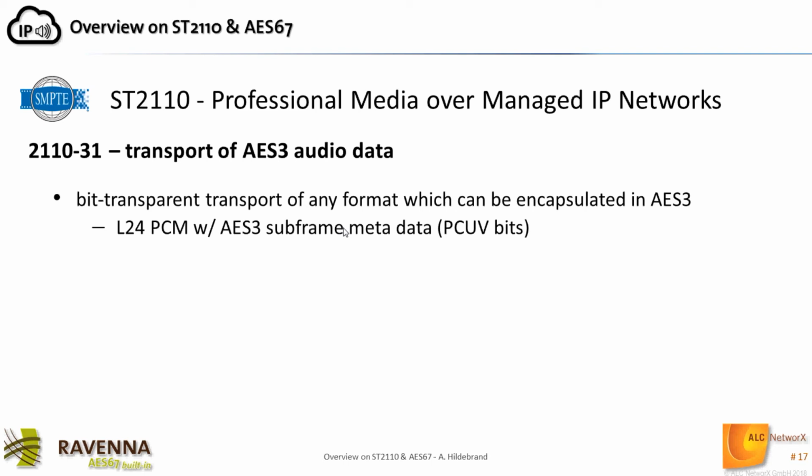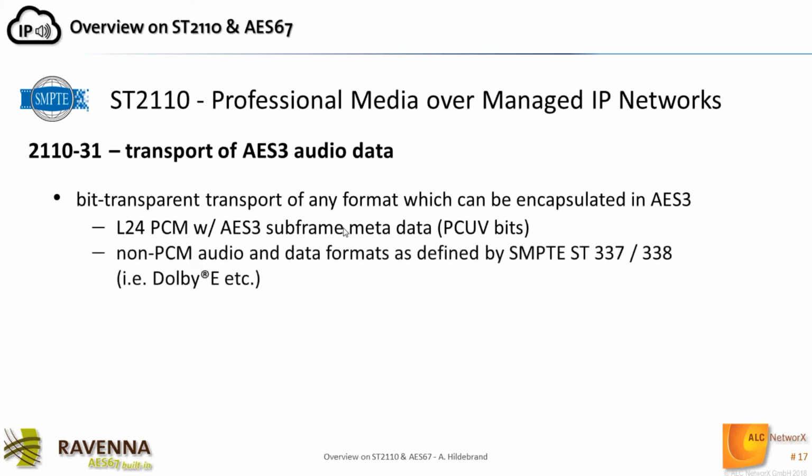Basically, it can transport any of these audio formats encapsulated in AES3, which also include the non-PCM audio and data formats as defined by SMPTE ST337 and 338, which also includes, for example, Dolby E and other non-PCM audio data formats. So this is the goal of -31, basically to transport every signal, every content which could be transported with the AES3 standard across a digital link.